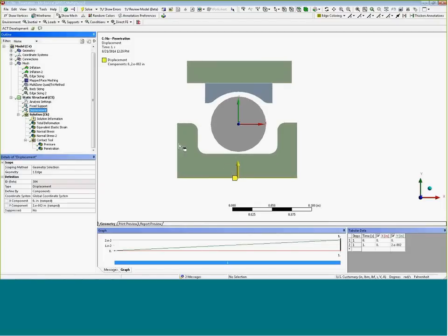Because if we did this, if this was a shaft in the center line, you would have to be making the shaft diameter larger. You'd be inducing a huge amount of hoop stress in here to try to preload and solve the model in this fashion. So if this was the type of problem that you're running, you couldn't run it or compress the O-ring this way.